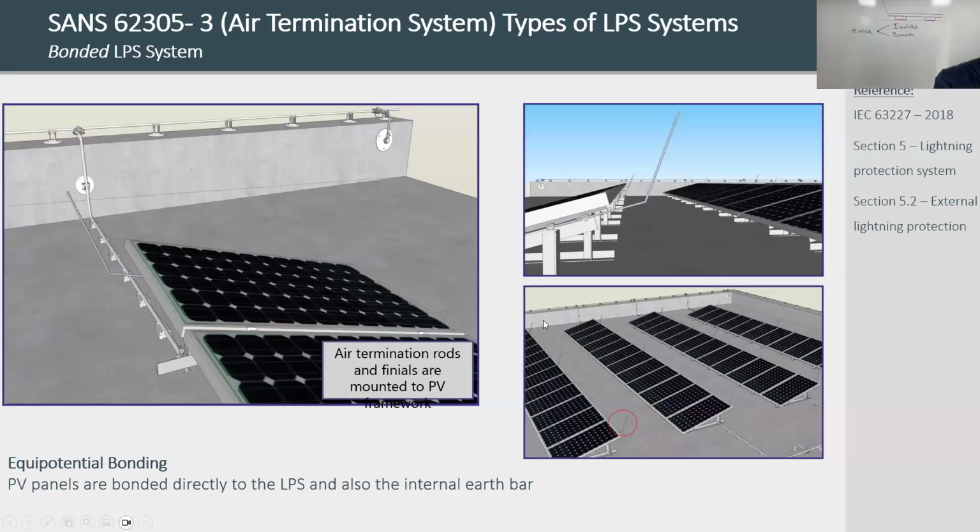Okay. So that is what we're facing in the industry at the moment, Carel, is that the roof and the bracket is where the big problem comes in. So normally what we do for IBR roofs, we've gone to such an extent now that when we test our lightning protection systems on a job, we actually test the EPC solar installation as well, because then we fix it while we're there. We make sure that we bond the solar panels to the roof so that it's done as per the standard.